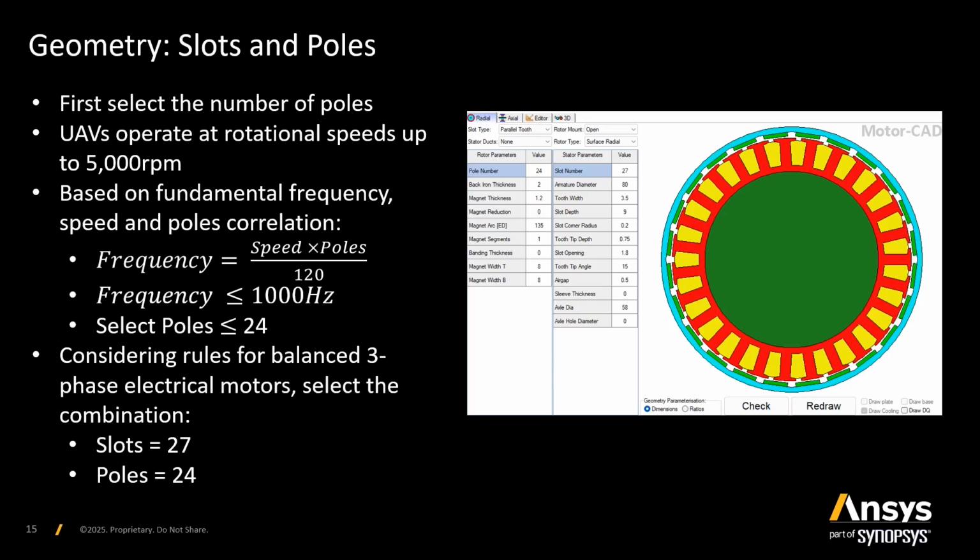So we can get more torque, and the back iron for the rotor and stator can be reduced. Also, with this configuration of a multiple of 9 slots and 8 poles, the cogging torque, which I mentioned earlier, is the main torque ripple component. It's mitigated significantly, so it's not going to be required to use skewing or any profiling of the poles for this topology.